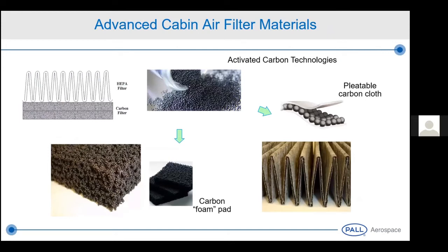Now I'm gonna go ahead and talk about the VOC part of the filter. So we use an activated carbon downstream of the HEPA pack in order to catch the odors in the cabin, generated within the cabin or ingested through the ECS from the outside environment.